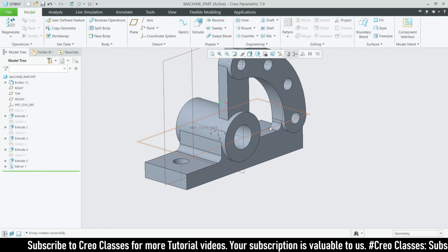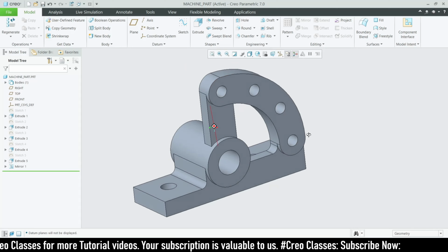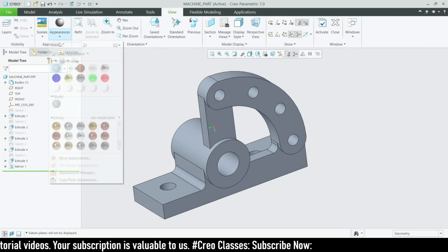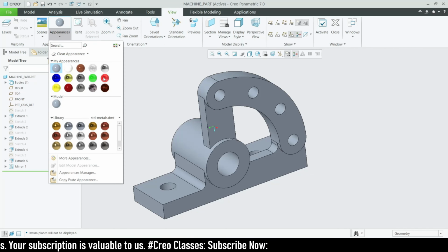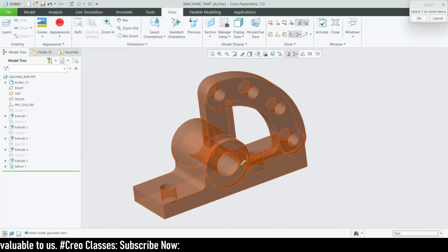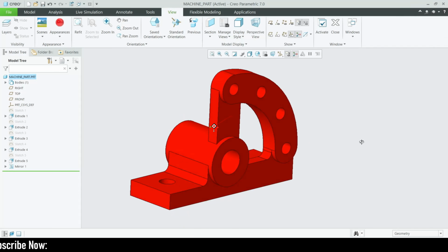So that's all guys. Let's switch off all the data planes. Let's give some appearances for our part. Go for view, appearances. I'm going to give red color as I provide red color for all the machine parts videos in our channel. So then click on OK.